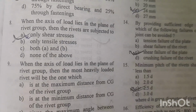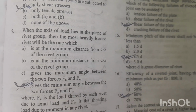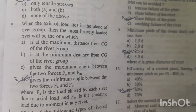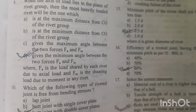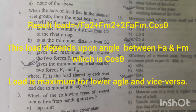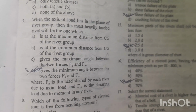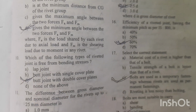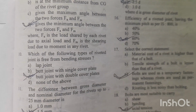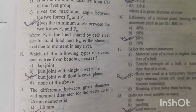Option A is right answer. Question number 9. When the axis of the load lies in the plane of rivet group, then the most heavily loaded rivet will be the one which gives the minimum angle between the two forces FA and FM, where FA is the load shared by each rivet due to axial load and FM is the shearing load due to moment in any rivet. Question number 10. Which of the following types of riveted joint is free from bending stress? Butt joint with double cover plates. Option C is right answer.